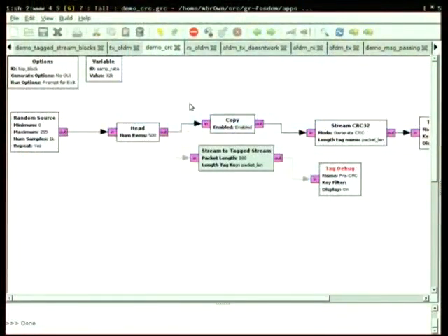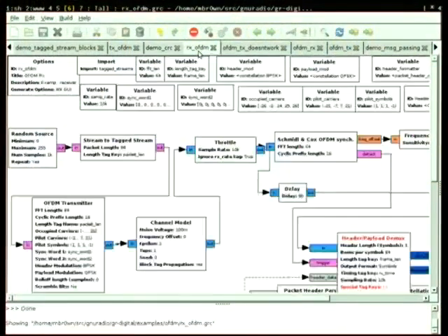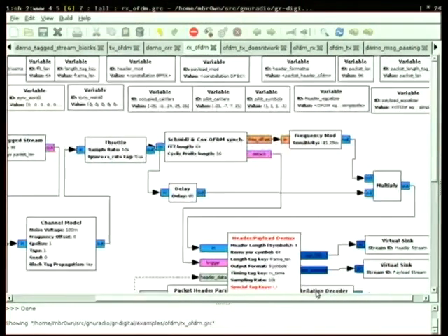Okay, so this is the receiver chain, and what I kind of skipped over a bit earlier was this part. I have this upper part of my flow graph, which will actually detect packets, okay? We use an algorithm called Schmidl and Cox because the way we set up the header is suitable for this.